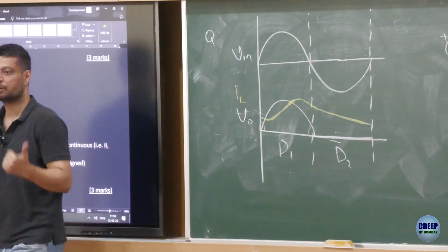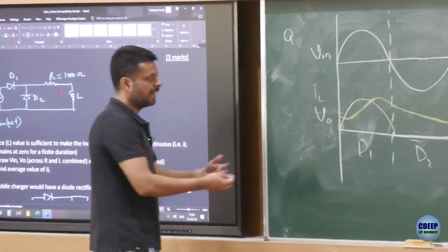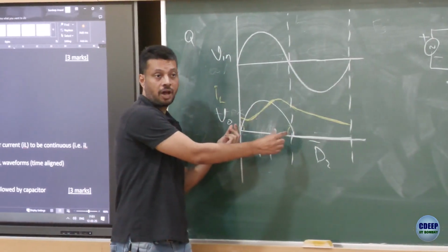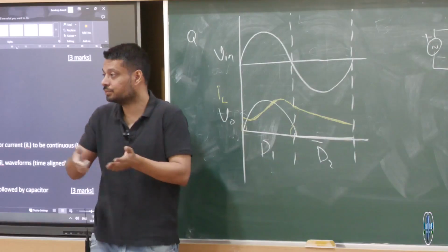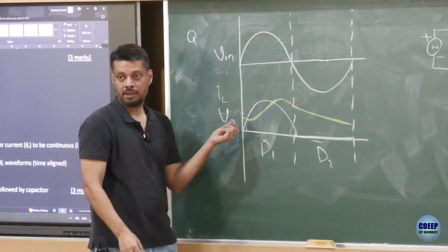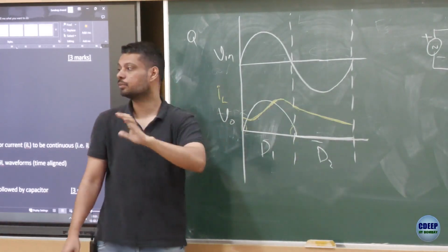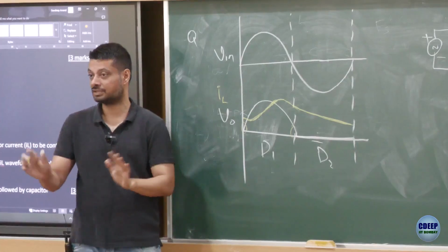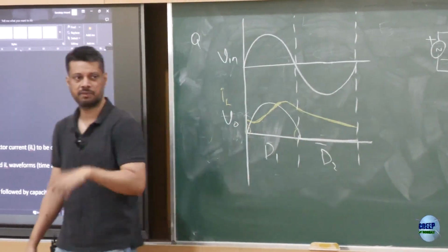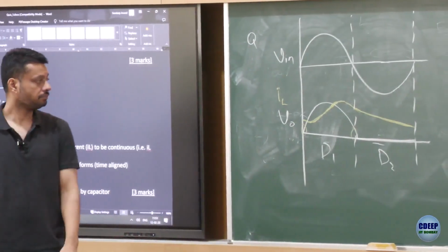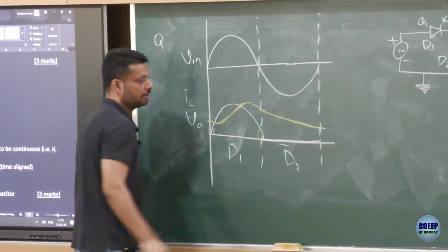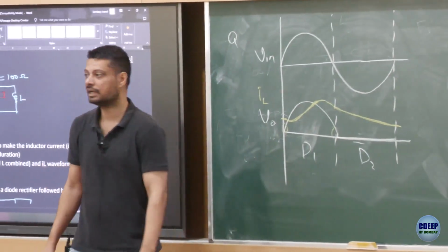Anyone has any other opinion? So the way I am thinking is here it's anyways falling, in the beginning and the end region, right? How much region of course depends on the equation and the exact values, but roughly in the beginning and the end region, this input voltage is very small, but there is an I into R drop. So voltage across inductor would come out to be negative. So it should still fall some way. So I have shown it as falling, and then in between it's sort of going up. Right? So roughly this is how it would look like. Of course, you have to draw it such that the starting point and the ending point are matching for this operation to be at steady state.